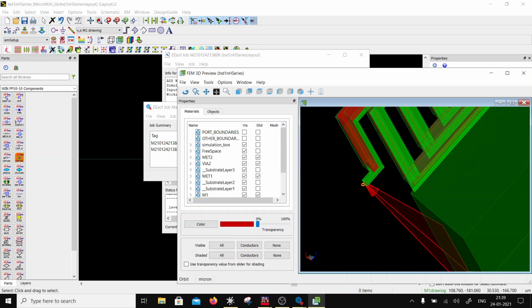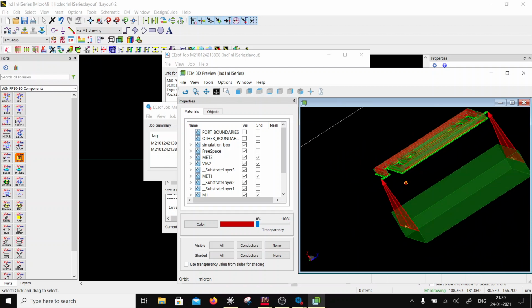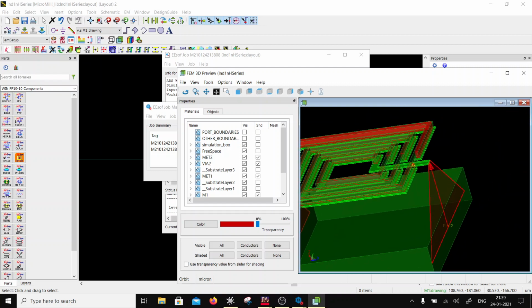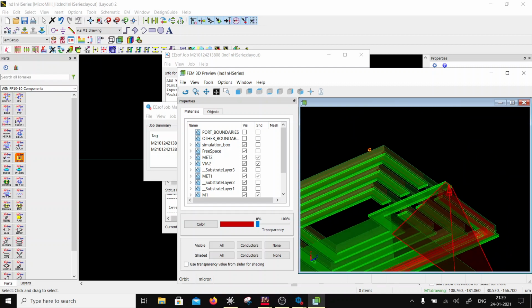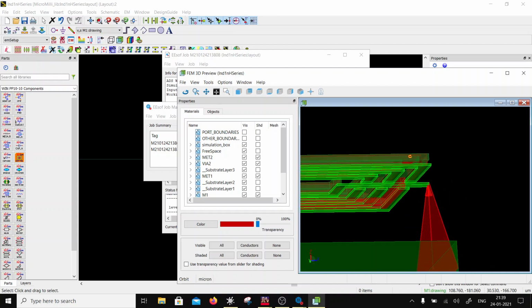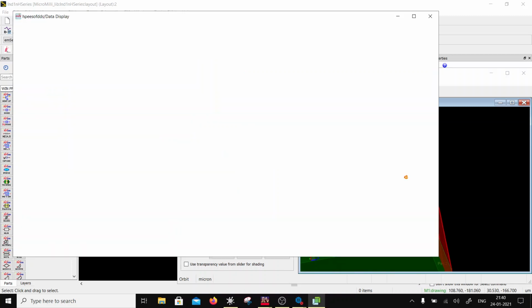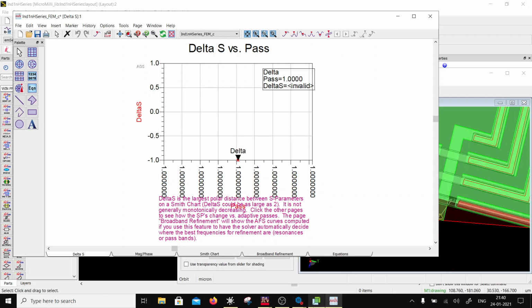So what you can see in this inductor is the following. You have port 1 and port 2. So let's see what is happening at port 2. In the case of port 2, you are coming in as an underpass, and in between there is air, which it is going to consider an air pocket, right? And it has tied. Okay, so we have come up with a mesh refinement.